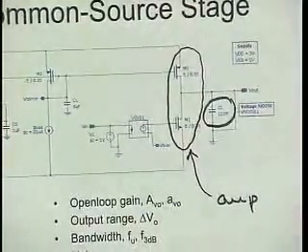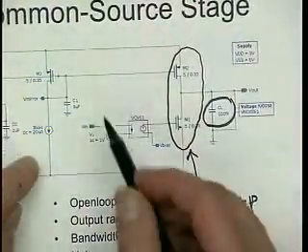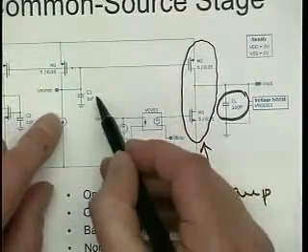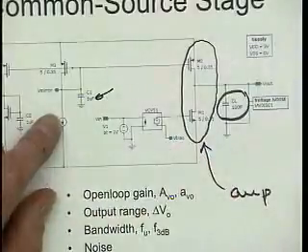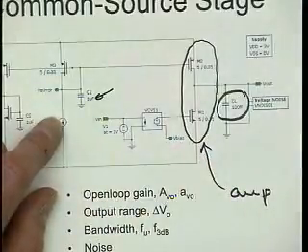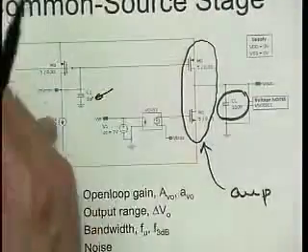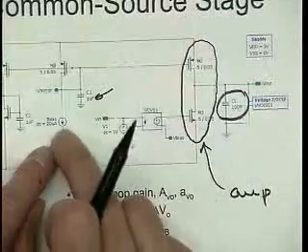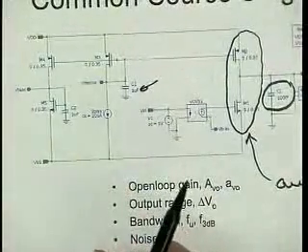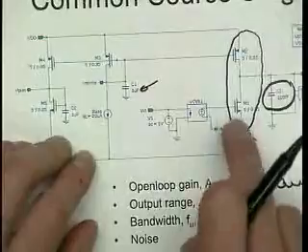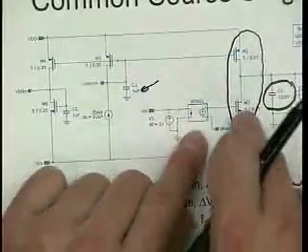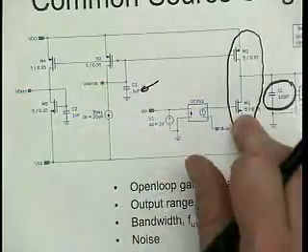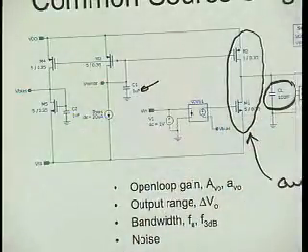Okay, so this thing here sets up the bias, a simple diode-connected transistor. Here I put in a huge capacitor. Why? Well, in order to get rid of noise, right? Because I really want to know what this thing does, not what my biasing network does. And a fixed source. And then, again, there is this old business of, heck, I need to bias this somewhere in the high gain region, right? So I cannot bias this at 0 volts. The transistor would be turned off. But what is the right voltage?